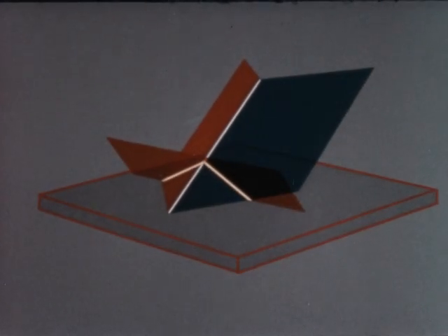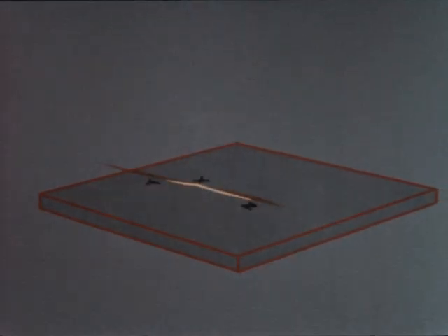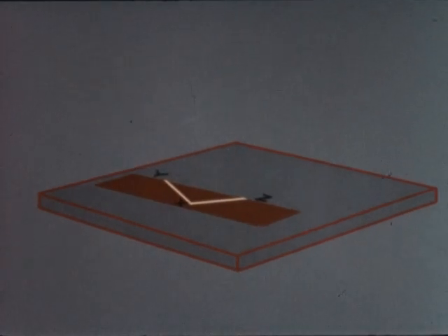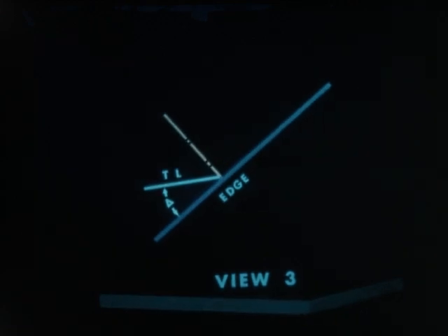The dihedral angle between 2 planes is measured by revolving the measuring plane to a true shape view position. The measuring plane is chosen perpendicular to the line of intersection of the given planes. To see the true angle a line makes with a plane, revolve the line about an axis perpendicular to the plane until the given plane shows as an edge and the line shows in its true length.